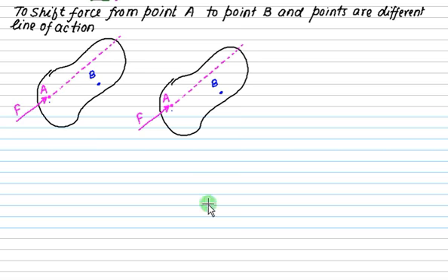Now again in mechanics we can take the concept of zero force. So what I do is, where I want to apply the force, I will apply one pair of forces, which is the same as the previous one. That is, this force is F and this force is F, and this total force is zero force. So it means that this system is the same as this system. That is a pure translational system.